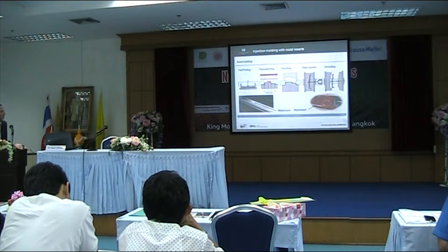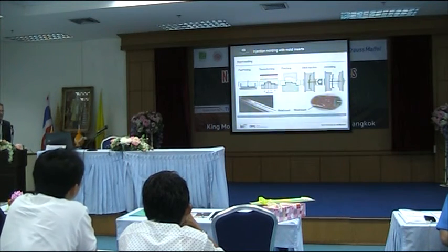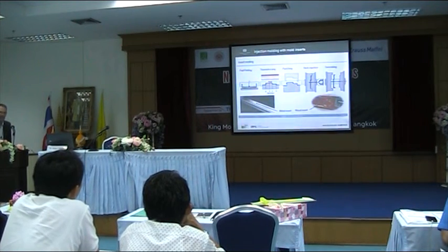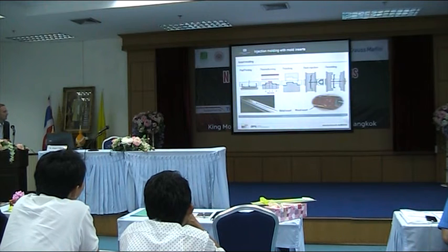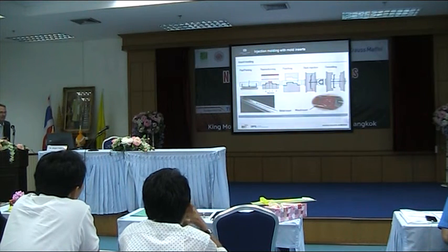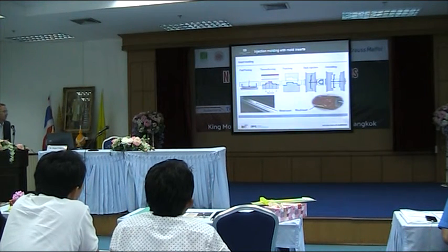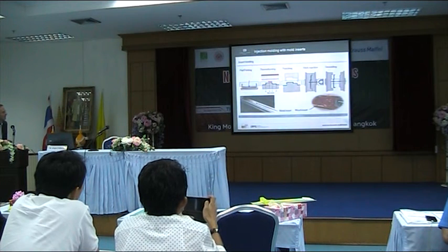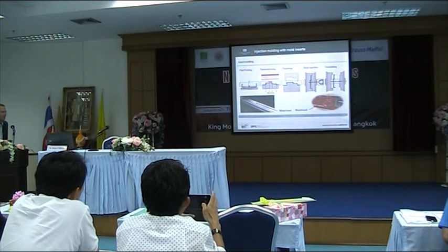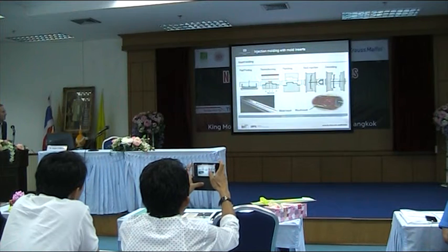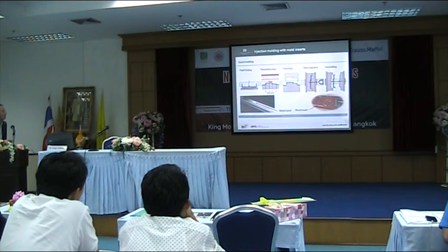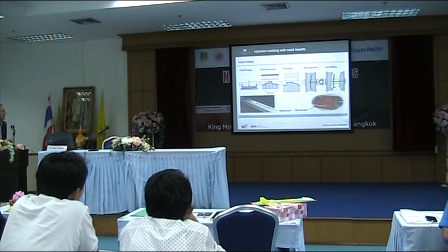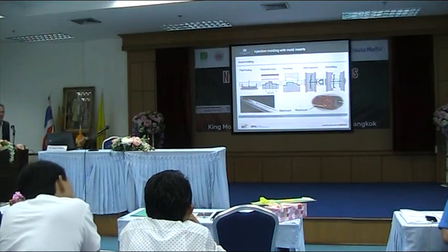Last but not least, something not for reinforcement: you can also use natural products, especially veneers, in thermoplastic parts to make decorative things. One typical example is so-called insert molding or in-mold labeling. You have some decorating material, you can print it, for example PET printing. It has some thermoforming already in the mold or outside. Then you have some punching to get the dimensions, and then you can back inject such parts.